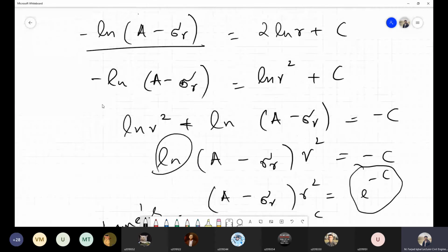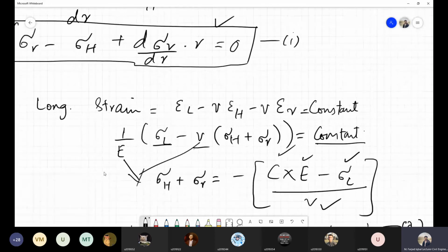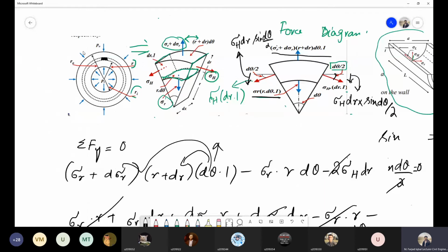Now, if I come back onto my original shape, and if I want to figure out the values of these two constants a and b in terms of radius, we have to come back into our original shape. Now, in this shape, if I want to write the boundary condition, I can say that at a radius of r is equal to ri, which is this particular radius, we have stress sigma r is equal to minus pi, which is this stress.